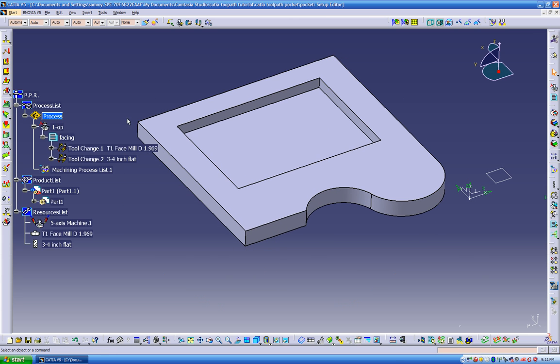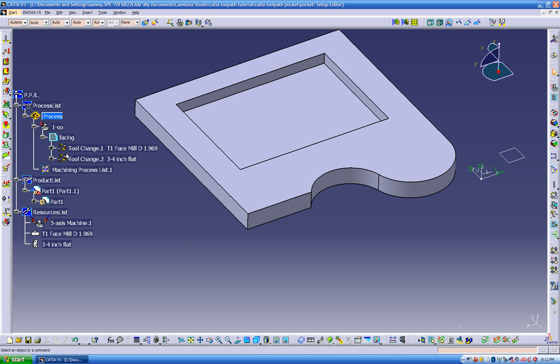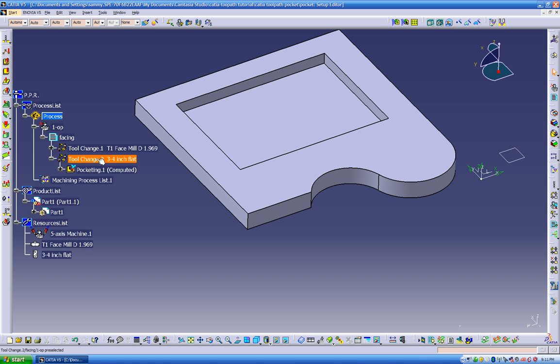And so what I'm gonna do first, I'm gonna machine this edge, and then I'm gonna machine this edge in here. And assuming they're gonna have two clamps to hold the part over here, then we're gonna stop the program and then swap the clamps and machine the leftovers. So let's make another contouring operation with this 3/4 inch flat.